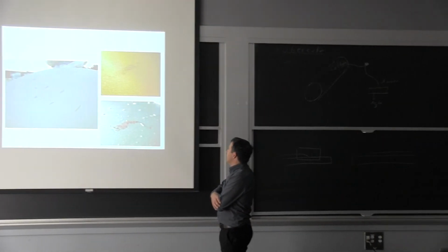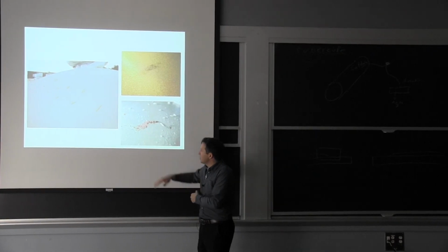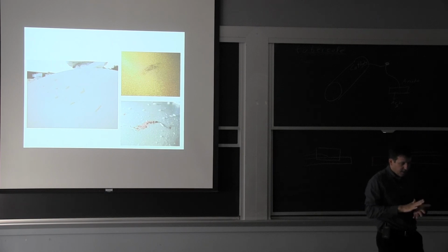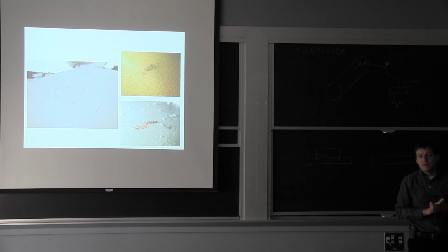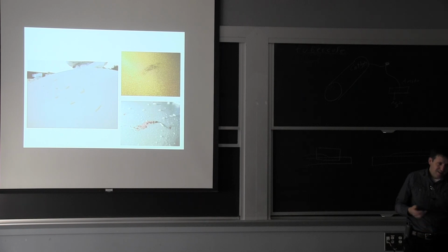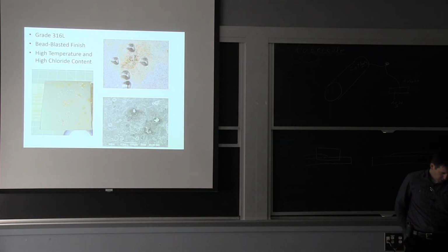A lot of issues happen with stainless steels. This one here was just a little test to show that it was contaminated with regular steel, structural steel. If I have a nice piece of stainless and I smear a little bit of regular steel on it, now when it's exposed to the environment, it can be just a very small amount, but locally it's going to start the reaction because I'm taking away some of the protective layer and replacing it with just regular carbon steel. So you have your best material, then just handling tools, cranes, chains, you name it. If they contaminate your product, you end up with corrosion.